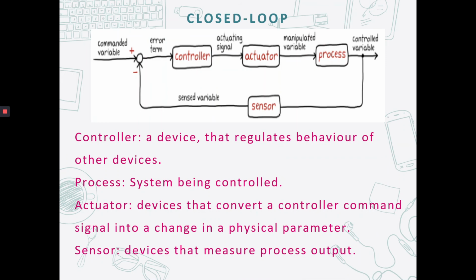So this is a closed loop system. The generic architecture of a closed loop system is shown in this figure. The closed loop system compensates for disturbance by measuring the output response, feeding that measurement back through a feedback path, and comparing the response to the input at the summing junction.